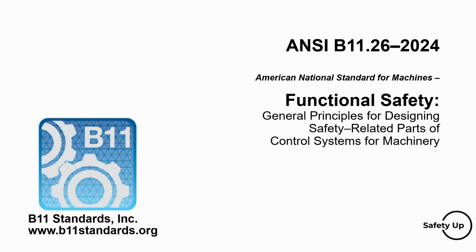The Design Requirements for Logic Devices section explains the role of logic devices in providing the relationship between inputs and outputs of the SRPCS and monitoring for faults. It covers safety interface modules, tampering and defeat considerations, failure modes, and reset functions. The Design Requirements for the Output Devices section addresses using relays, contactors, and fluid power systems. It provides design requirements and considerations for these output devices, emphasizing the importance of proper air preparation, filtration, regulation, and lubrication to maintain the reliability of pneumatic systems.